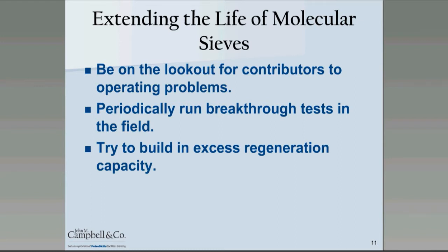And what I feel is very important is to try and build in excess regeneration capacity by way of building in standby time. By building in excess regeneration capacity during the design phase, this means that your regeneration circuit will be larger, but it gives you some margin in case you run into issues and you have to reduce the adsorption time. The only way you can reduce adsorption time is by being able to complete a regeneration cycle before the adsorption cycle finishes. And if you want to reduce your adsorption cycle time because you have, say, more water in your feed, that means you have to complete the regeneration cycle quicker. And one way to achieve that is by having standby time in the design.